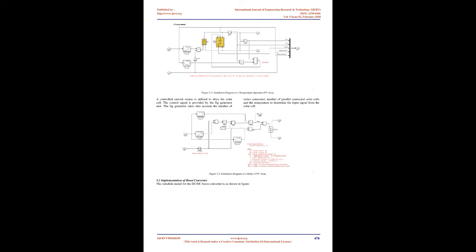In photovoltaic systems the IV curve is nonlinear, thereby making it difficult to power a certain load. This is done by utilizing a boost converter whose duty cycle is varied by using an MPPT algorithm. A boost converter is used on the load side and a solar panel is used to power this converter.